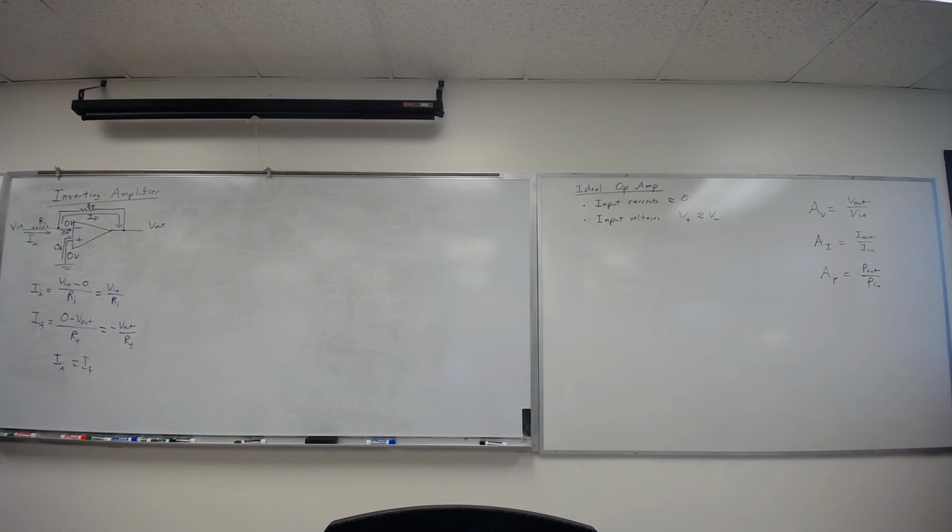Okay, so my two currents are the same, because I come into this junction, there's no choice. So that means I can set Vn, you know what? I usually put an N on this. I don't know why, but I'm pretty sure that's the way it is on the sheet, so I'm going to write it that way. Okay, so Vn over Rn equals minus V out over RF.